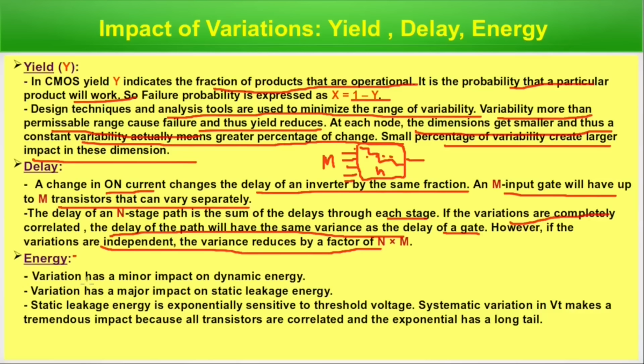Now energy. Variation has a minor impact on dynamic energy. It has a major impact on static leakage energy. Static leakage energy is exponentially sensitive to threshold voltage.